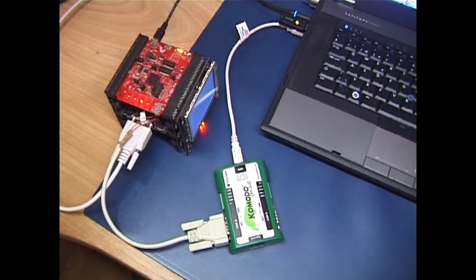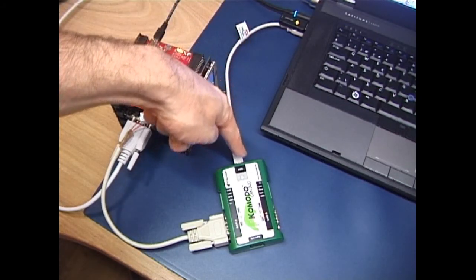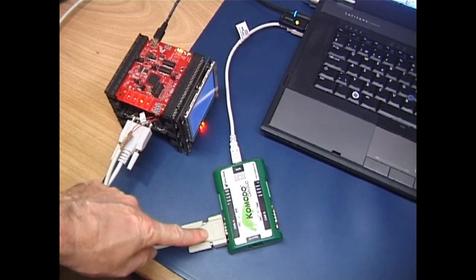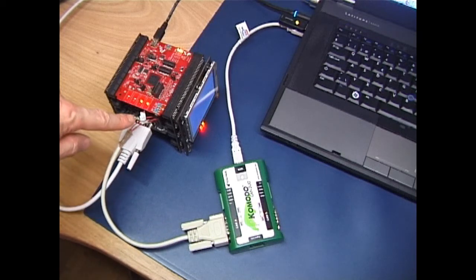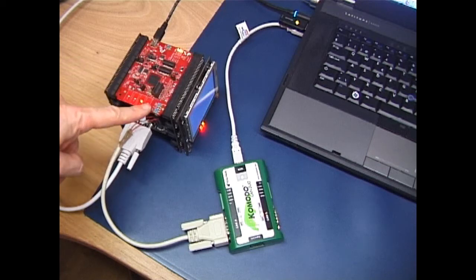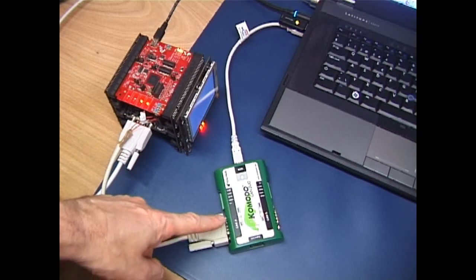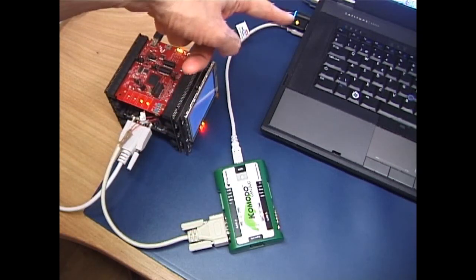which means every time the uTasker simulator or the program running on it sends messages to the CAN0, it will be passed through the simulator and appear on the physical bus so that it can be received by the real hardware. In the opposite sense, any information sent in this direction will then be received by the uTasker CAN simulator.